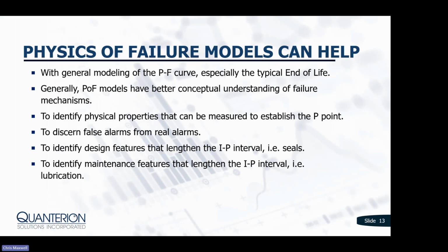To improve your P point on your curves, physics of failure models can help, right? If you know the physics behind the failures, the mechanisms, POF models help you to refine your PF curves. They help you to implement corrective actions. They help you to refine your design features and your maintenance features to lengthen the life of your parts in your systems.